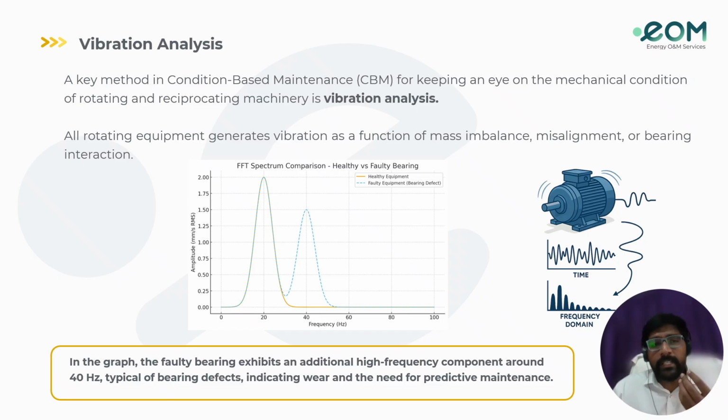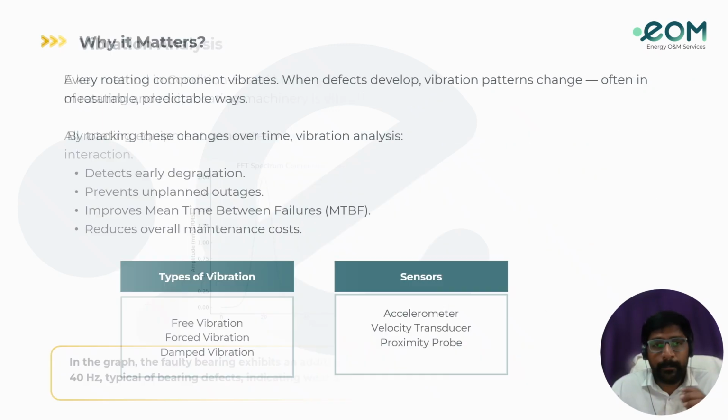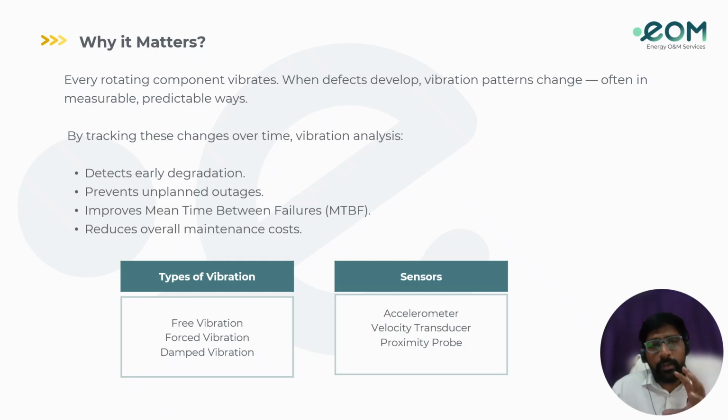So now let's see why vibration analysis matters. Because every rotating component vibrates, when defects develop, vibration patterns change in often measurable and predictable ways. By tracking these changes over time, vibration analysis helps in detecting early degradation, preventing unplanned outages, improving mean time between failures, and reducing maintenance cost as well.